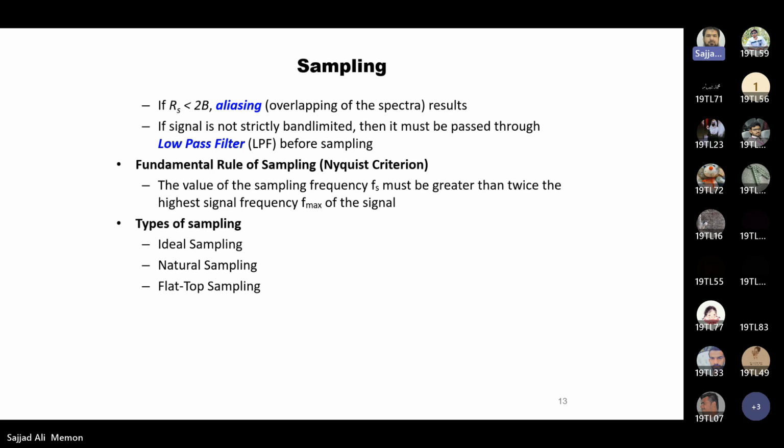Let's suppose we are trying to filter out the signal at frequency f1. It might have a cutoff frequency equal to f1 plus 100 hertz, 200 hertz, maybe 0.5 kilohertz. So the cutoff frequency will always be greater than the frequency of interest that we would like to filter out.